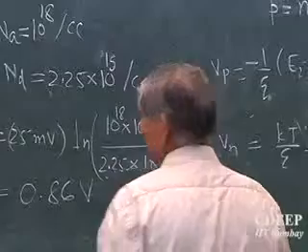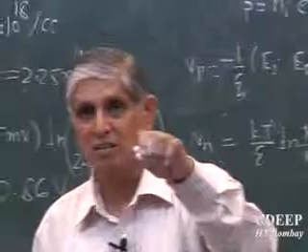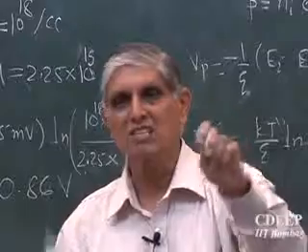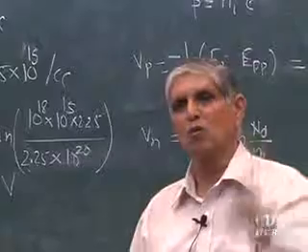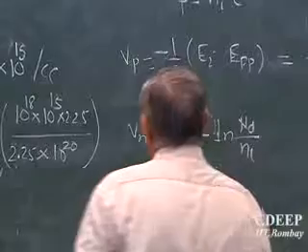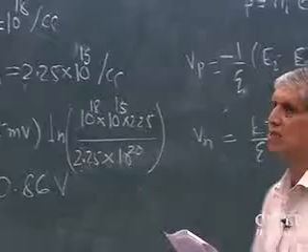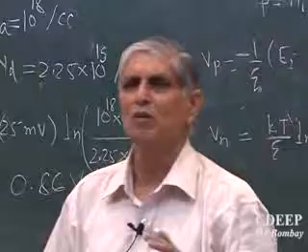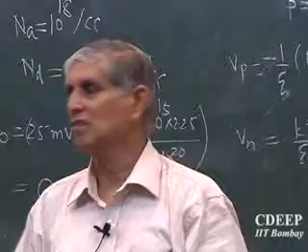There is also a possibility that all dopants may not get ionized even if you dope. That means they do not all replace silicon. There is no vacancy where they can sit, which means what will happen? They will sit in existing sites and actually create defects. So again, you never get the full quota of electrons and holes in the conduction and valence bands. This V0 value which I am showing you is to show that the built-in voltage is typically of the order of 0.6 to 0.9 volts, never beyond that. This is the range in which devices will operate.